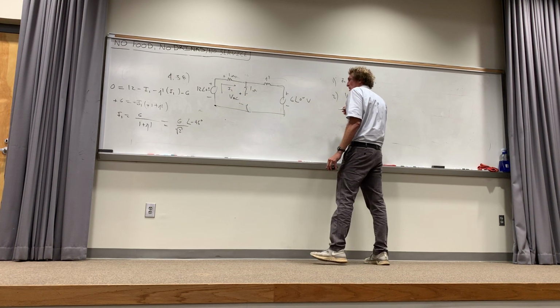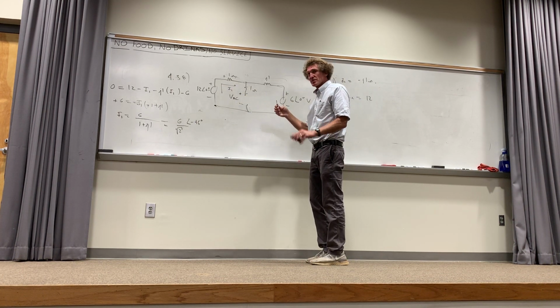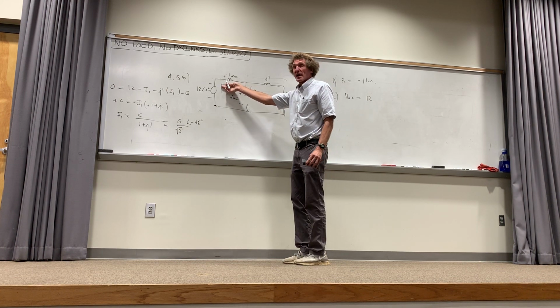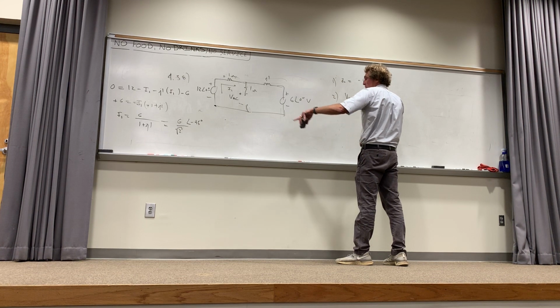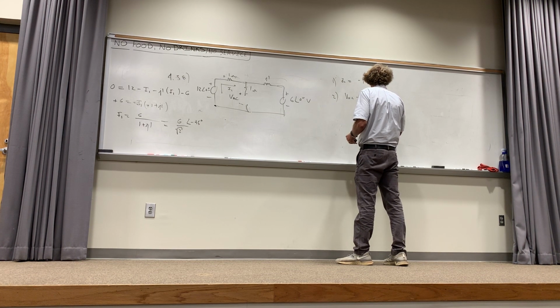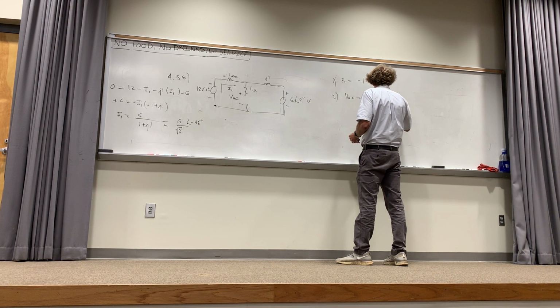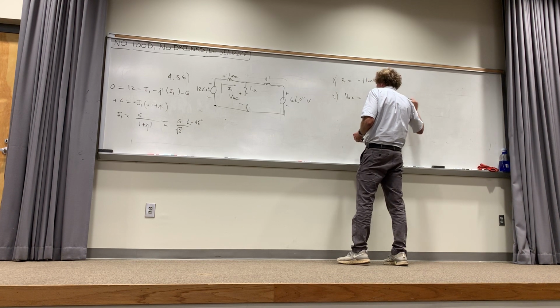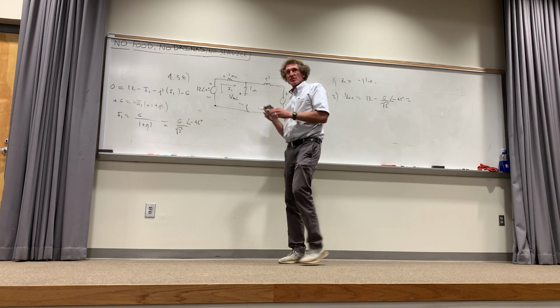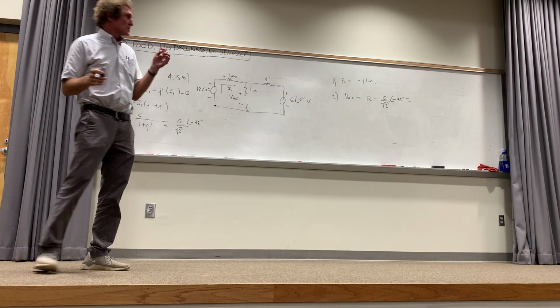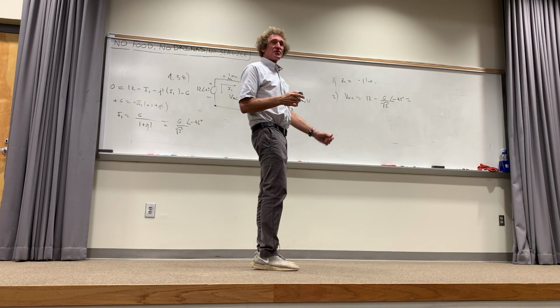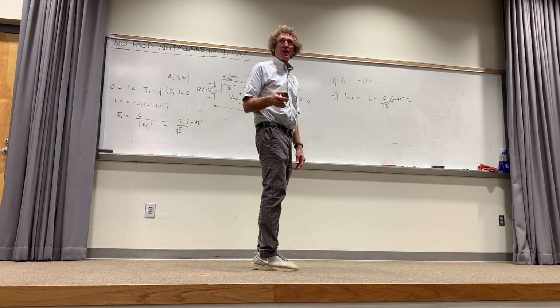Here's where you should get out your calculators and make sure you can do this. Then I'm going to have a decrease of minus 1 times I1, or minus 6 over the square root of 2 at an angle of minus 45 degrees. That means I'm going to get an open circuit voltage with a magnitude and an angle, right? A non-zero angle. So what does that come out to be? Do it on your calculators. You'd be surprised how many people stumble right here.